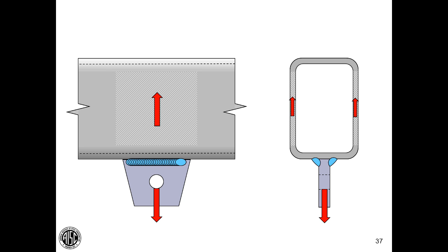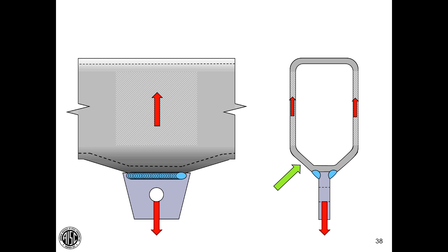The weld is uniformly loaded along its length. This is not a strength problem in that regard, but once again we have a load transfer challenge here. The deformed state helps us see what's happening. I trust once again that you can see the straining at the toe and the straining at the end of the length of this weld.